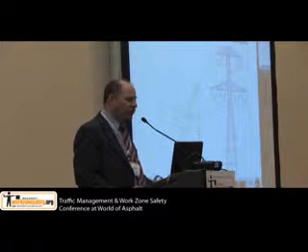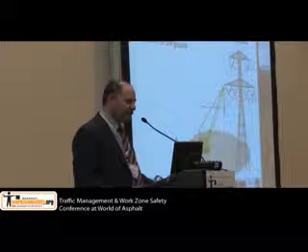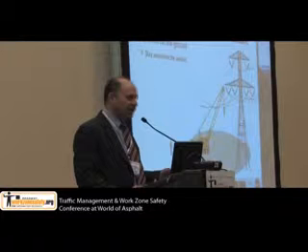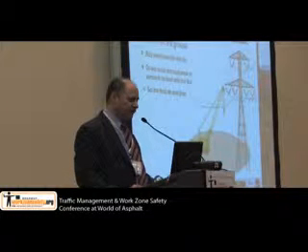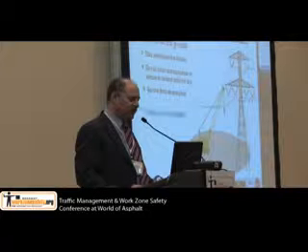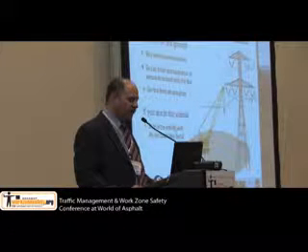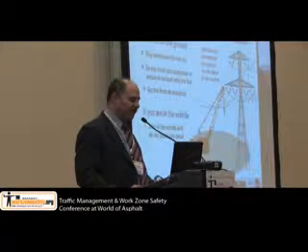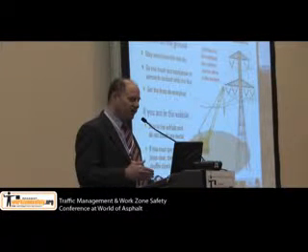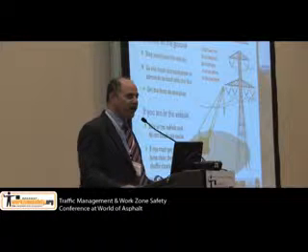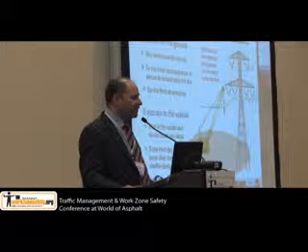If, unfortunately, you do contact a power line, if you're on the ground, you need to stay away from the vehicle. Do not touch the equipment. Get the line de-energized, and if you're in the vehicle, you should stay in the vehicle and not touch any metal. And if you get out, jump clear of the vehicle and then shuffle slowly away. Does everybody understand why you do that?